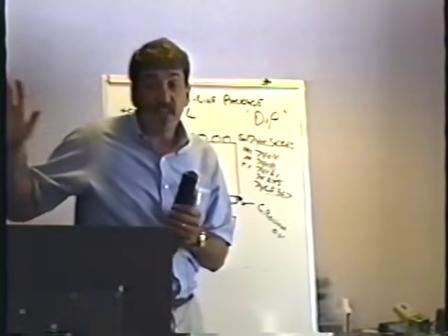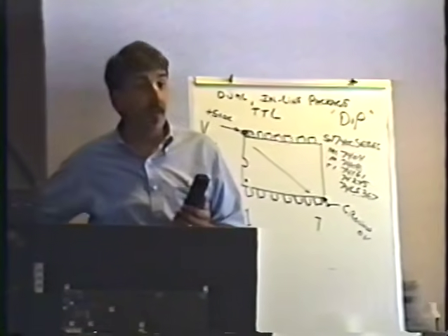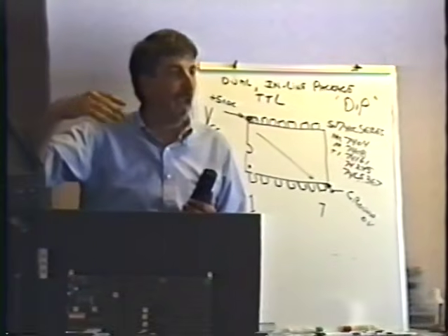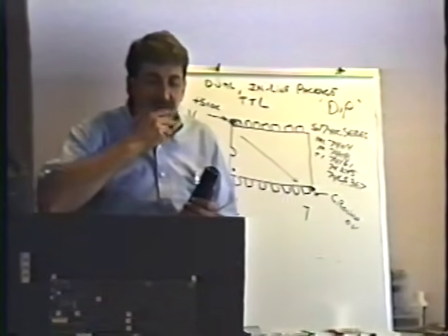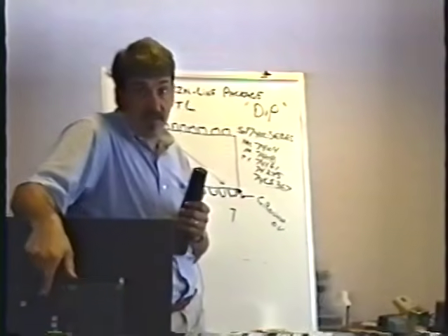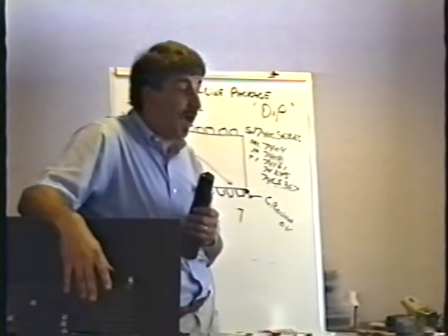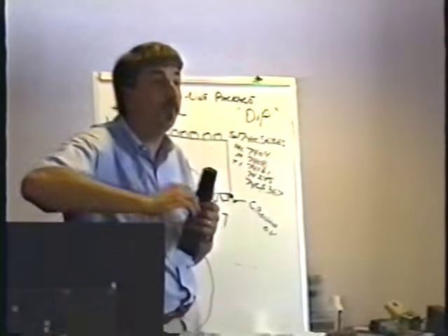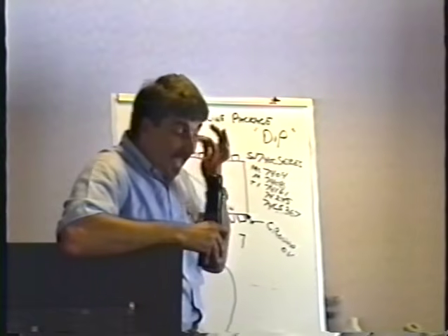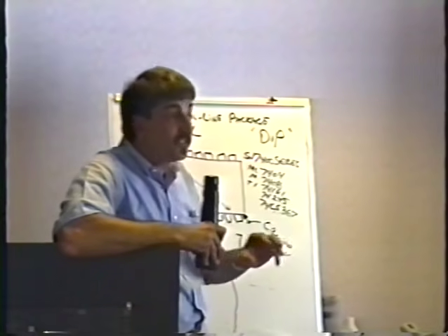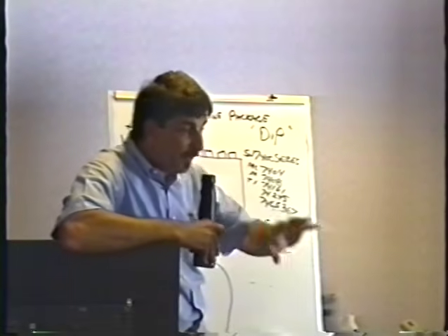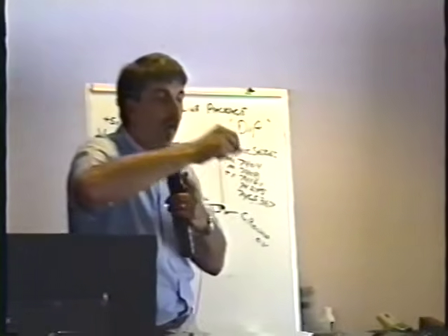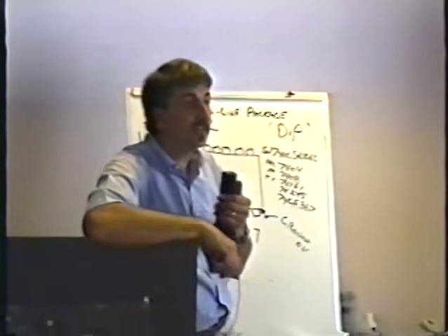Many games have a self-test in them. You've probably seen it. You fire up a game, it says ROM okay, RAM check, or whatever. If it tells you that one of those devices, one of those ROMs or something that's in a socket is bad, it may be that, or it may be some other chip, but you certainly want to try that first. Another thing that you can do is to get another one of the same game and try swapping all the chips that are in sockets.